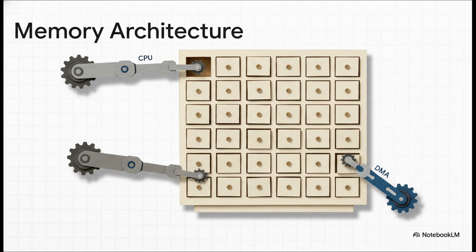Now, the memory management unit efficiently organizes the internal SRAM by structuring it into independent 32-kilobyte banks. Because of this clever hardware design, the CPU and the direct memory access, or DMA, channels can actually access data at the exact same time. There are zero hardware bottlenecks, as long as they're looking at different memory banks. That is an absolutely massive boost for any of your data-heavy tasks.